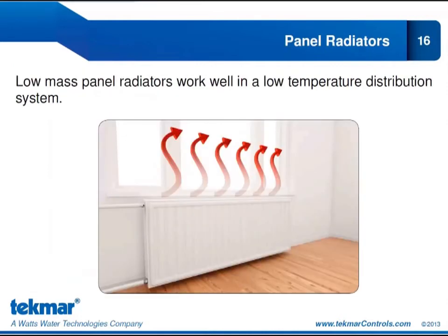Well, one thing we have is a low mass panel radiator. So traditional radiators are not a good selection for a geothermal application. And that's just because they require very high supply water temperatures. However, low mass panel radiators do work well with the lower entering load water temperatures. You have to size the panels so they deliver the design space heating output using the recommended design temperature of, let's say, a maximum of 120, which is the case for most heat pumps.